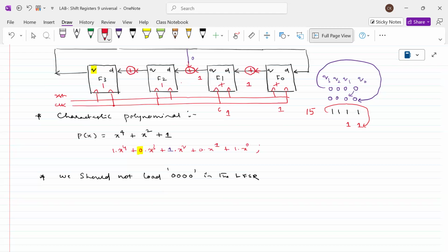This is already shifted information, taken from the previous one, and this is the existing one that will be thrown out. This one and this one, what will happen? What is exclusive OR for 1, 1? 0. 0 will come here. That 0 will occupy this position, and this one will come here, right? The 1 will remain at this point because we have not applied the second clock.